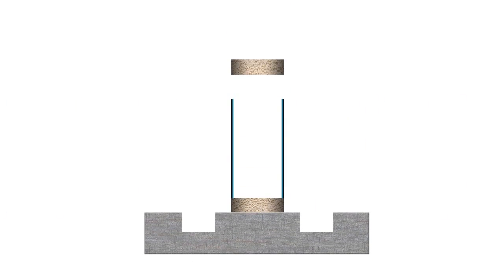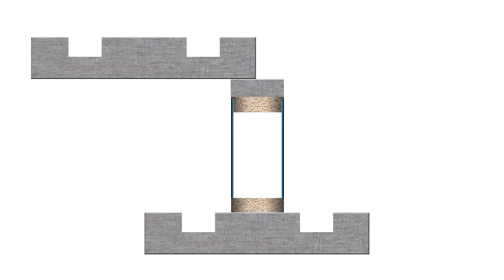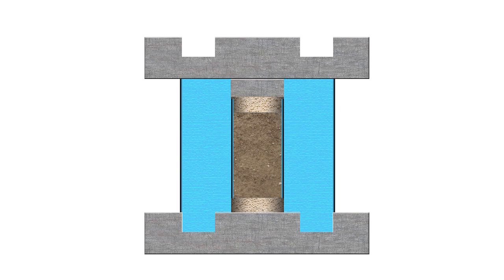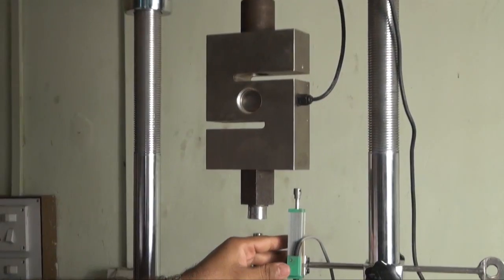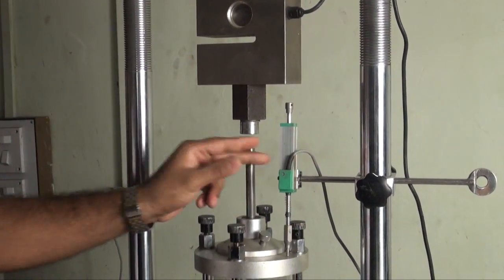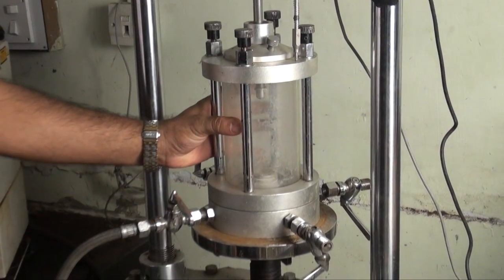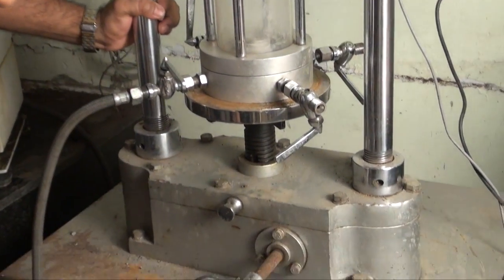Well, next up is the tri-axial test. Its origin can be traced back to the USA, where the scientist Kalman used it to study the behavior of rocks. Cylindrical specimens are used for the test. In the first stage, called the consolidation stage, the specimens are subjected to an all-round confining pressure on the side, top and bottom. When the consolidation is completed, a deviator stress is applied at the top of the specimen so that it can be sheared. This second stage is called the shearing stage.